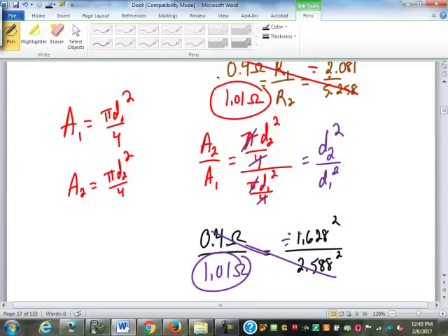In the packet that you guys have, on page 277 of that packet, is a table that gives the standard gauges and their diameters. Now, I've been using millimeters just because it's simpler for me. In English units, a mil is a thousandth of an inch. So if it says 101.9 mils, that's really 0.1019 inches. That's just under a tenth of an inch, just so you know.